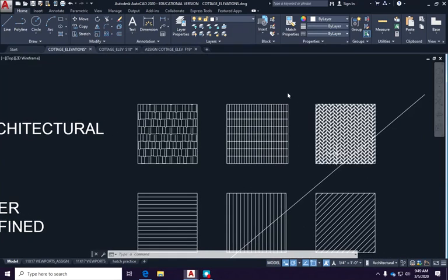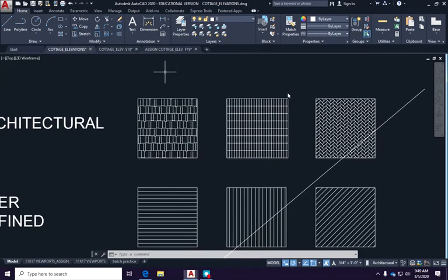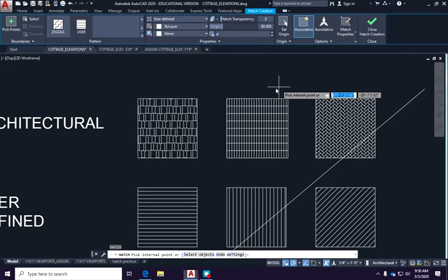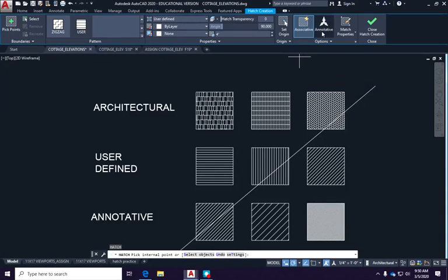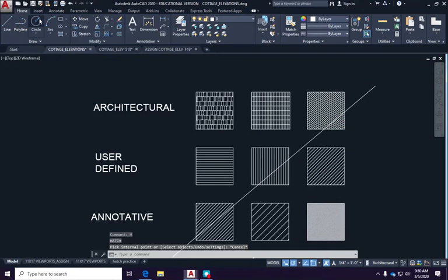What if our shapes only work in annotative when it's on? I am going to save, turn off the video, and come walk around and look at what you're doing. But the biggest goof up, where things don't look the way you think they should, is if you have this annotative either on or off and it's not supposed to be. Only use annotative with annotative, those two right there. And I do this all the time too. I'll start doing stuff and go, why is it coming in like that? Okay. So save, and I'm going to